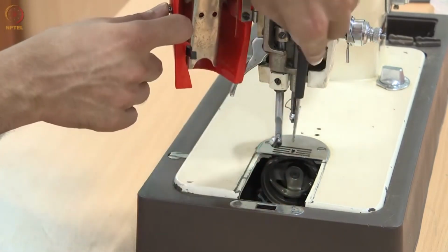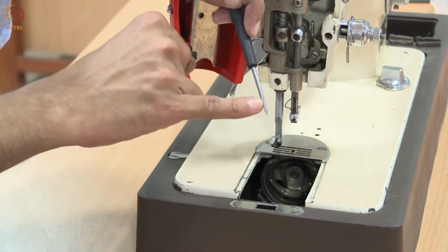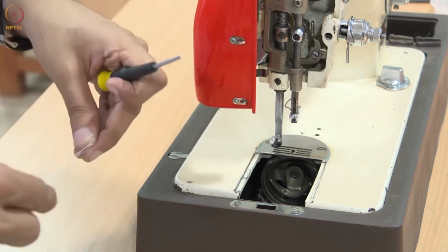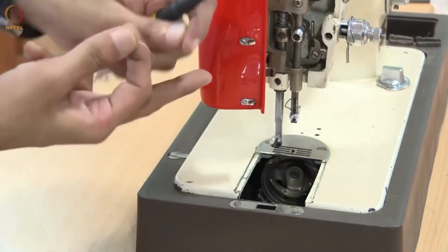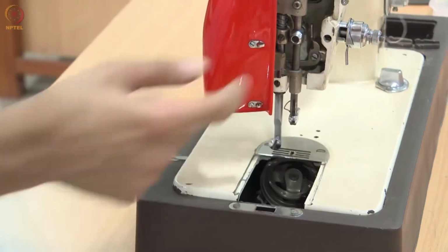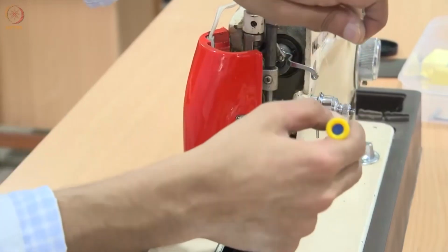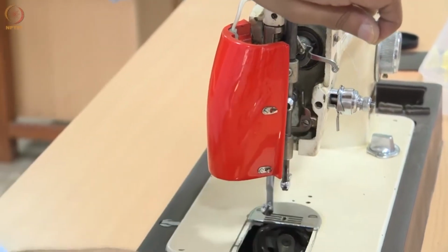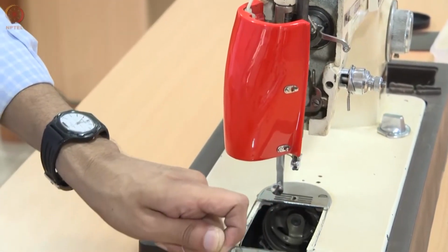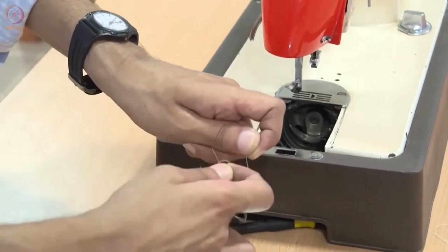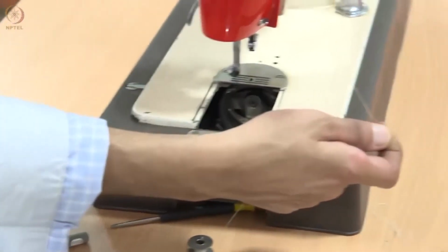So this goes and punctures the cloth, right? Remember the needle has an eye hole at the tip of the needle. So you have the thread that goes through. Basically the needle punctures and goes through the cloth. As the needle punctures, it makes a loop through the cloth. Now you need another thread that goes through the loop. Even doing it by hand, you can see how difficult this is, doing it with two hands. So now we have basically a lock stitch. This is what we call a lock stitch.